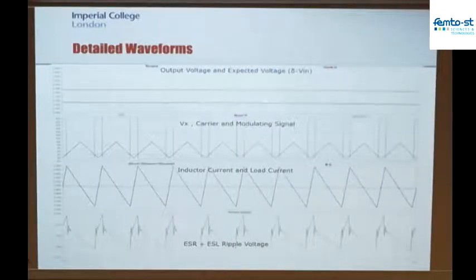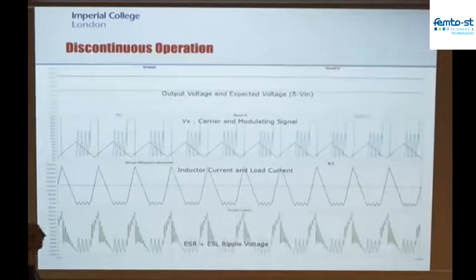You can see there's a little bit of ripple on top of there, and that's because I'm not filtering this thing perfectly with that LC filter. And part of the reason for that also is that the LC filter itself, the C in that LC filter, is not a perfect C. It's got some parasitic components associated with it, and that is basically showing through in the behavior in the output. But it is essentially doing exactly what I think it should be doing. Not quite perfect, but very close.